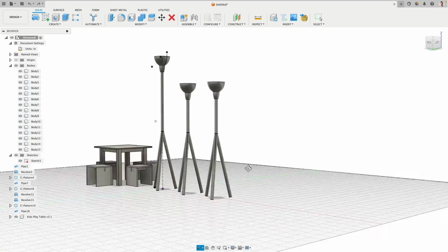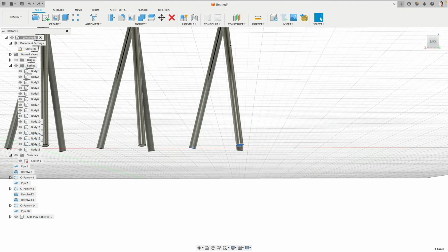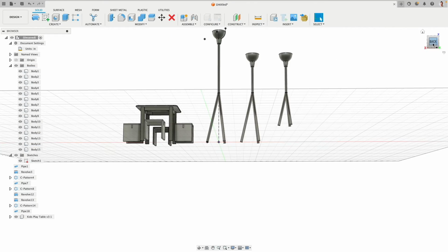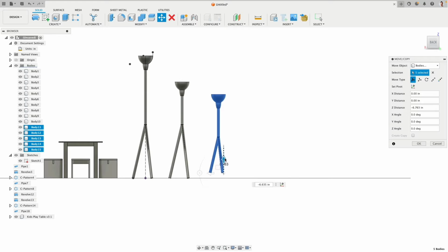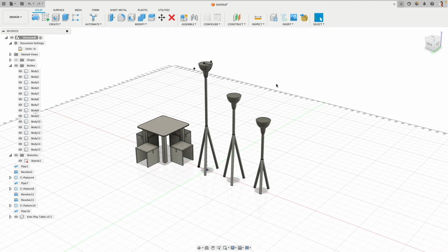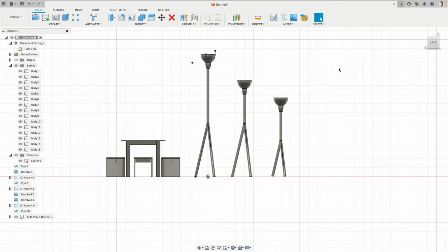Oh, actually, hold on. I want to make the legs shorter. I think I can select these caps. Yeah. Then I go to the press and pull this up. You see now how this gets shorter. Very good. Select everything. And now I'm just hand putting it down. There. And we see actually how easy it is to use this direct modeling to very quickly explore some design variations.